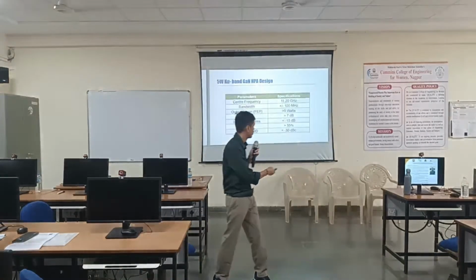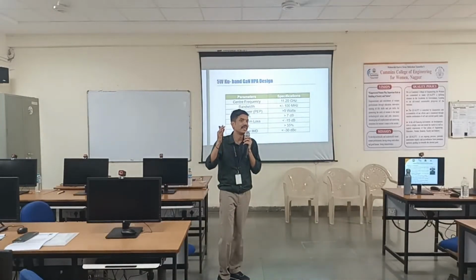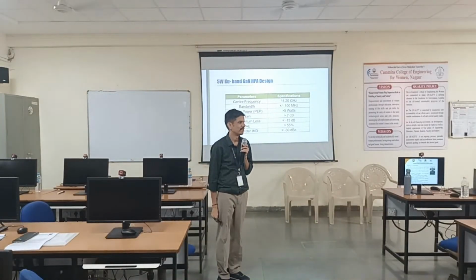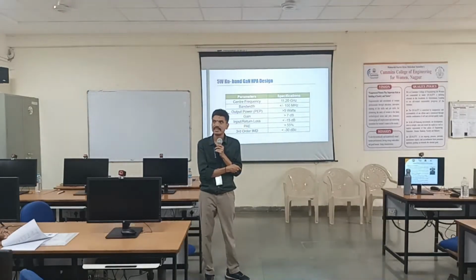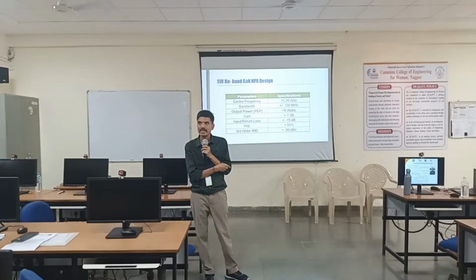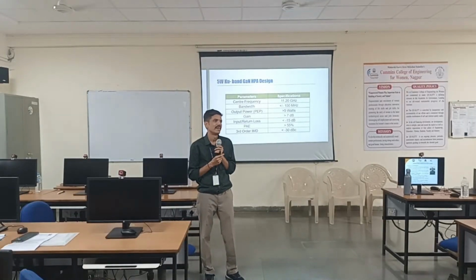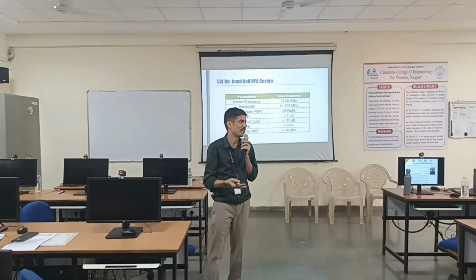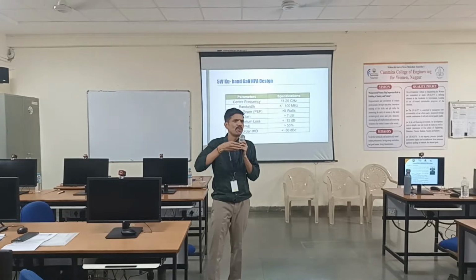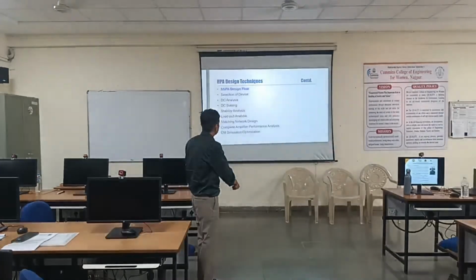Let's say you have a gain of 7 dB. If you make it uncompressed, your gain will be 11 dB. So it is actually an 11 dB amplifier, but why are we calling it 7 dB? Because gain is compressed by 3.5 or 4 dB. Then the question comes to your mind: why compress at all? Why are you compressing it? So there are a whole lot of questions. For that reason, you have to look back to this curve.